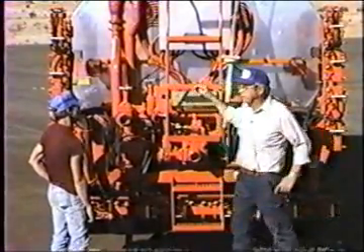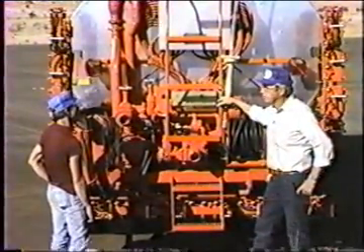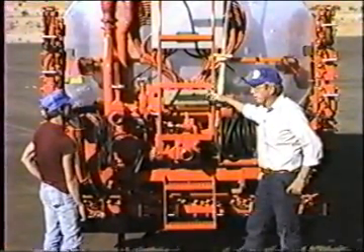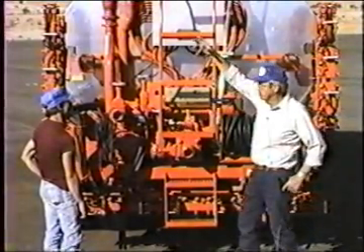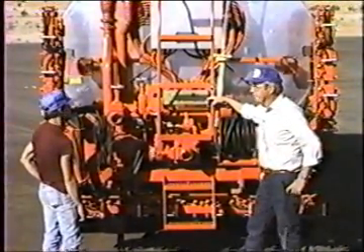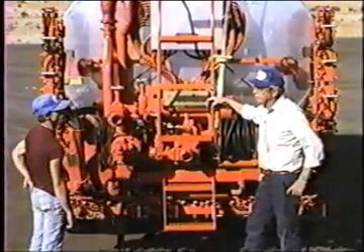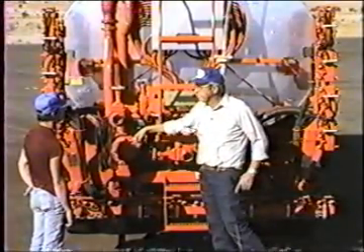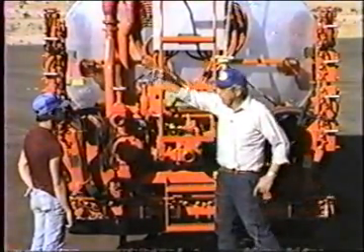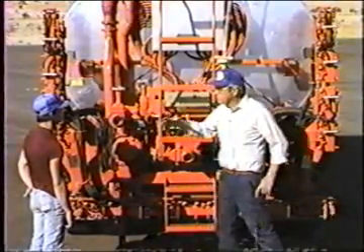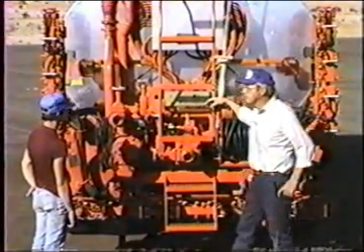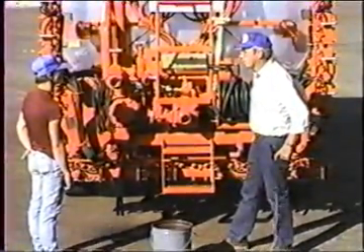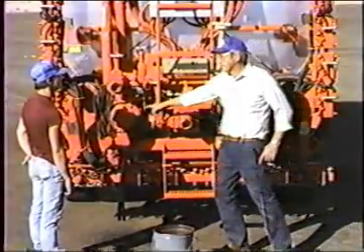So if we're going to pump into a tank that's got questionable valving, questionable hose, piping, maybe it's plugged up, and that's very common in asphalt tanks. Maybe there's a pipe going someplace and somebody's left it plugged up. If we have any question at all about the condition of the piping, we should always pump in the forward direction so that we have the safety of the relief valve in the pump. If it feels a blockage, it'll relieve in the pump and before it pops the hose, before it makes a big terrible mess. If we're going in the reverse direction doing that, pushing through a closed valve or a plug valve over here, this pump doesn't relieve.